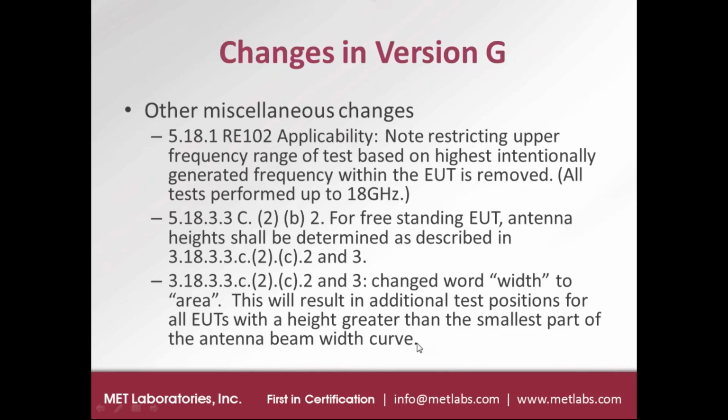So in the previous versions, you may have tested 3 antenna positions from left to right on the floor in order to cover the full width of an EUT. Well, now you may end up doing 6 or 9 if the EUT is also a tall EUT in order to cover the height of the EUT.